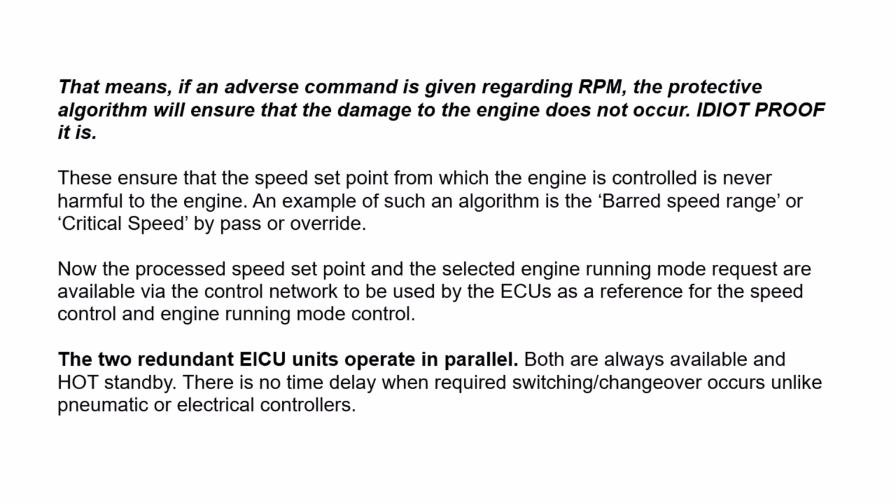Two redundant EICU units operate in parallel, which means both are available, in hot standby. We never know which one is in use, A or B, but you can check it later on. I'll tell you how to check it. But the operator will never know. In case one EICU for some reason is not working, you will get an indication by the LEDs, but the other EICU will take over without you realizing.